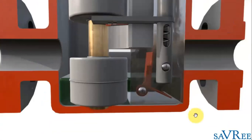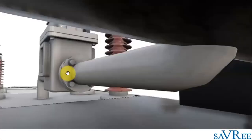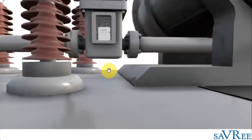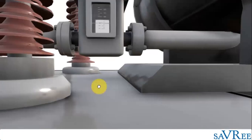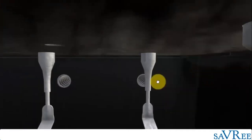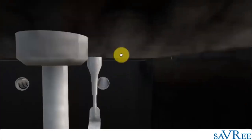Now remember, the tank, if we go back to our model over here, the tank is below the Buchholz relay. And what you have to imagine is below this section here, or below the top of the tank, everything should be covered in the insulating liquid. That's why it's called a liquid immersed transformer. If I go inside, actually, I might be able to show you. Yeah, we can see the connections here from the bushings. So this whole tank, this whole area should be totally flooded with liquid or insulating liquid.